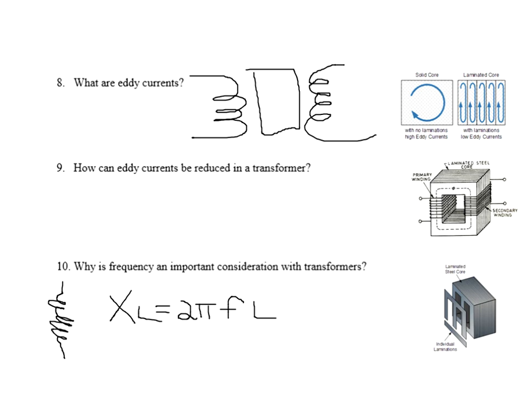Well, we have to be careful. Transformers are designed to work around a certain frequency. If you use a low-frequency transformer that is designed to have a very, very small amount of ohms in it at lower frequencies, when you increase the frequency, you're going to get a lot of ohms, and that'll restrict the amount of current that's flowing in that primary. So frequency is an important consideration with transformers because they're designed to work around a certain frequency.